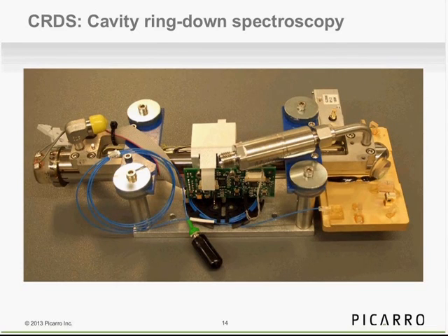Okay. So moving on to the technology itself, cavity ring-down spectroscopy is also a laser-based absorption technique. This is a picture of our cavity itself. I was going to show it in scale to the people in the room, but it's about 30 centimeters long in total. The volume of the cavity is about 35 standard cc. It's a three-mirrored cavity, so it's got a triangular configuration.